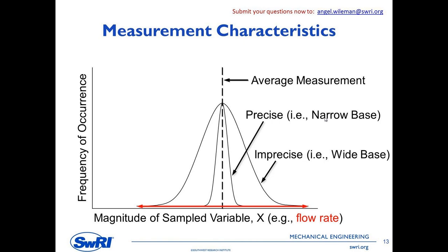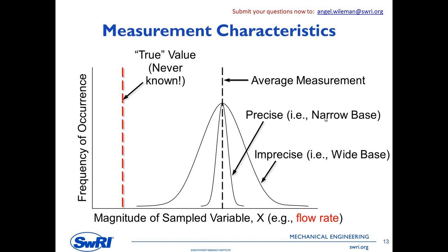The fun part in all of this is you don't know what the true value is. You have a measurement, but you can never actually know what the true value is. Yeah, I know the hardware store says you can, but this is a different thing. So when you measure against a reference, the calibration facility provides that reference value, and that's going to be considered to be the true value, even though even the calibration facility has uncertainty associated with it.